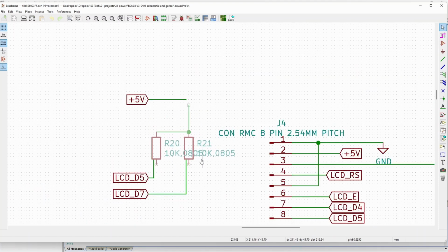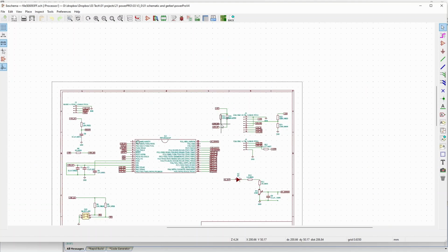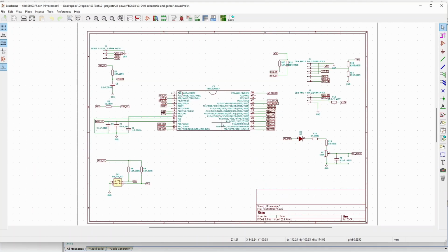Or else you might have made it 1 in the code, but it will not go 1 because it's an open drain connection. So pulling it up will make this pin go high. If you make it 0, this pin will be pulled low. So always make sure that you have selected the pins correctly, and if you have any doubt, take an individual pin, toggle it high and low, and check it using a multimeter. Because I made this mistake a few times with a few of the controllers where the output pin will not go high.